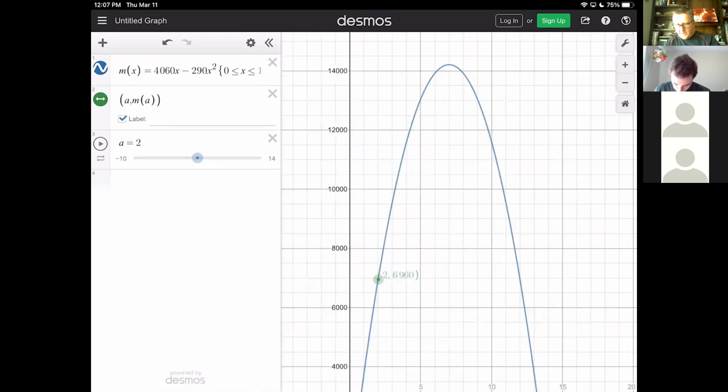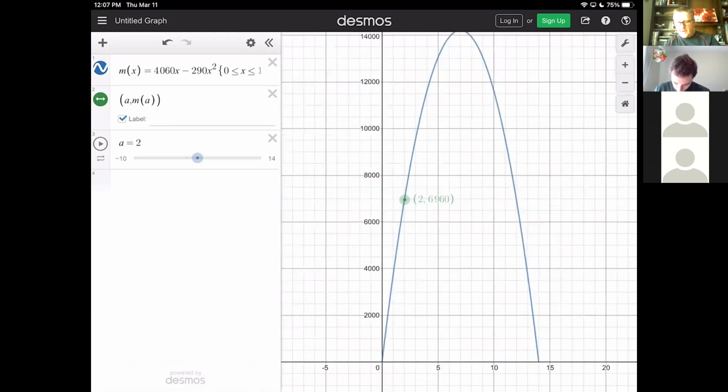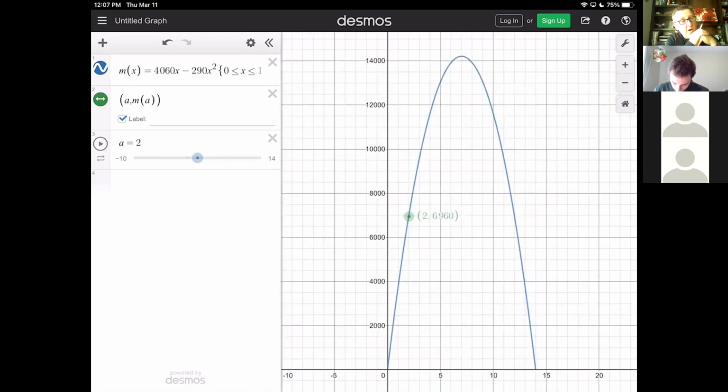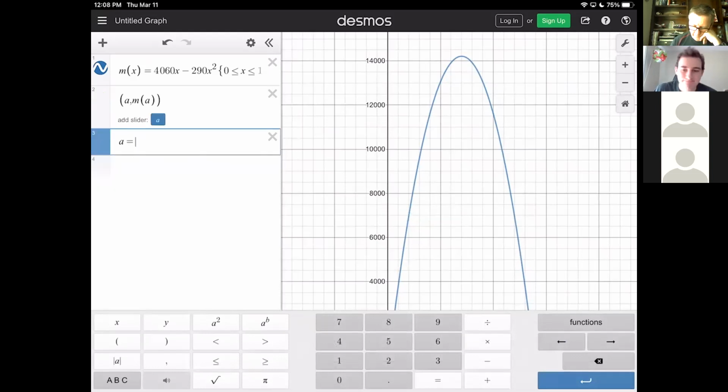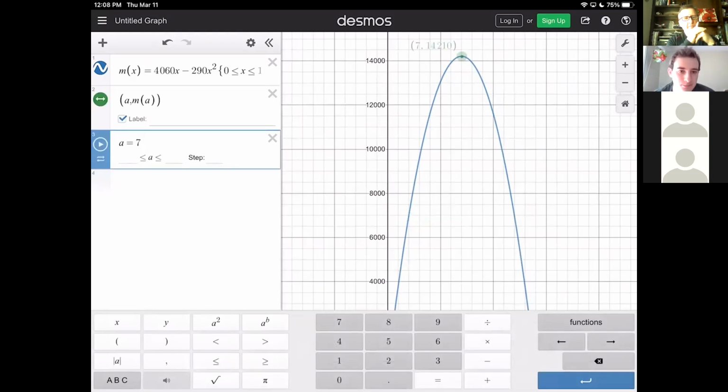Again, do you see why you want a diagram? Why this is so cool to have a diagram? Because the diagram allows you to see all the moments, every possible place there's moment. And of course, that top one is the one we're after, because that's the max. Where do you notice that is? Where on the beam is that? It's exactly in the middle.